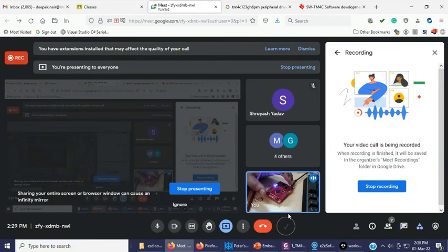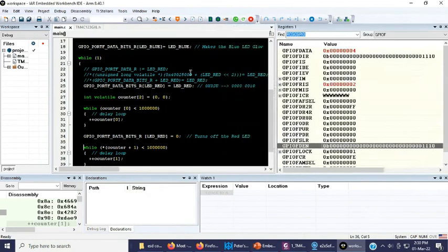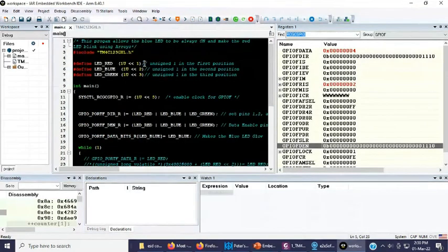So you can keep on changing the program according to your use, and for that today we learned how to simplify the program using, first, the header file, and second, the bitwise shifting operation to enter a particular one in that particular bit position. Apart from that, we also learned how to use bitwise ORing to change certain bit positions without disturbing the rest of the bit positions.